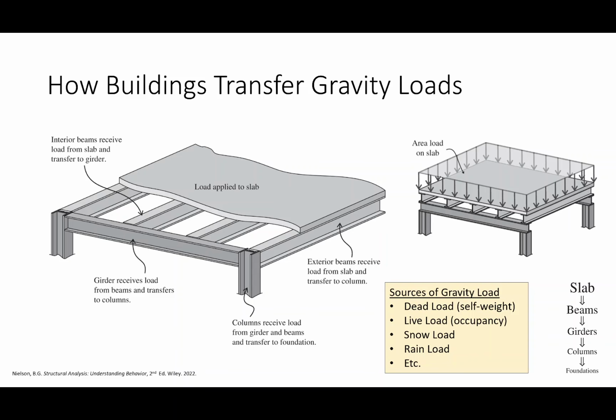But in all seriousness, the books represent a different occupancy for the building. So if you think about it from a structural design perspective, the floor system in a library has got to be much more stout than the floor system in this building, right? Because the loads are different, right?